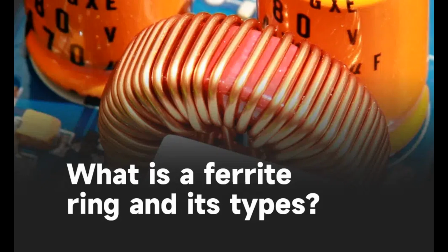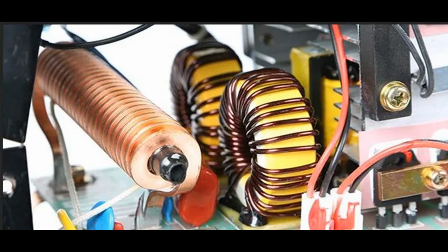6. AC and DC behavior. Direct current, DC: for a steady DC current, the inductor eventually reaches a state where it behaves like a short circuit, low resistance, as the magnetic field stabilizes and no voltage is induced. Alternating current, AC: for AC, the inductor continuously opposes changes in current, causing it to exhibit inductive reactance, which affects the impedance of the circuit.